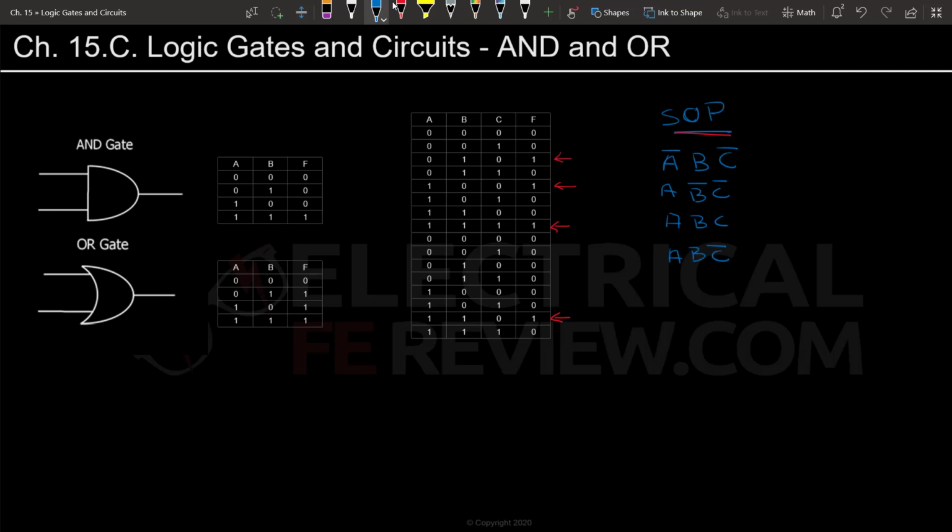Whenever we write a variable that is multiplying another, remember that that is an AND connection. So that's to keep in mind when we're going to draw the circuit. For now, we're just going to write the function f as the sum of these products. So here's the function completed. Just like I was saying before, the multiplications will become AND connections, and the summations will become OR connections. So let's see how to do that by actually drawing the circuit.